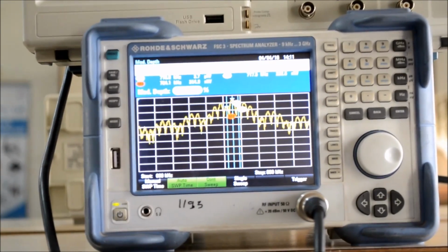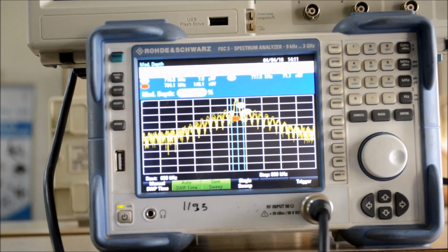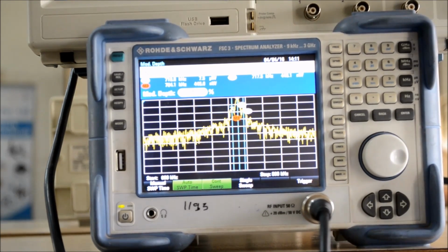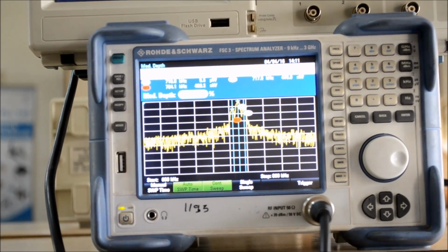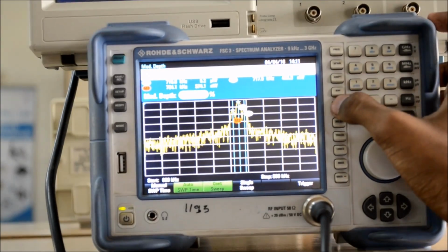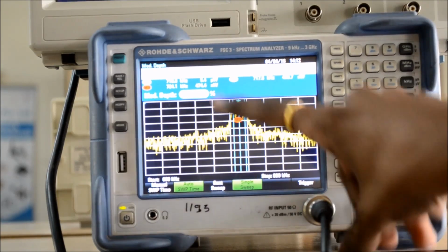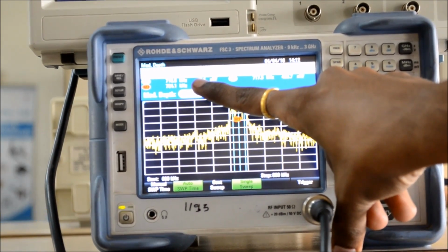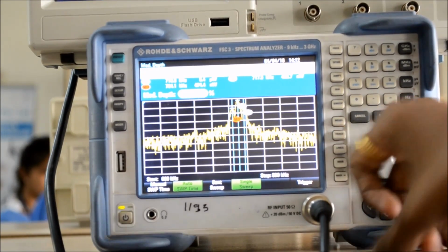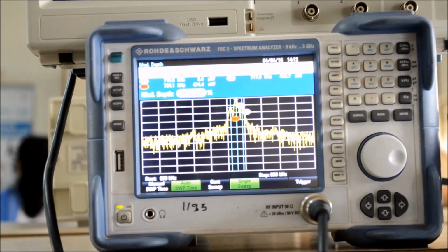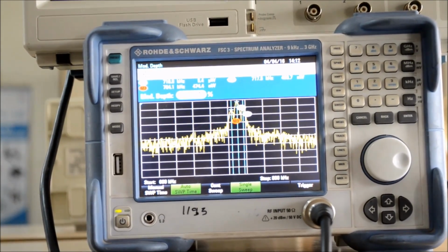Now, you can just observe, as I'm changing the value of DC, the modulation index is changing and the spectrum is also becoming different. So by changing the DC bias and by using the sweep function, you can single sweep it and find the values of modulation index, the LSB power, the USB power, the power of carrier. And repeat this by changing the DC value again and again and find 5 or 6 readings. So this is how you are supposed to perform the experiment of AM transmitter.